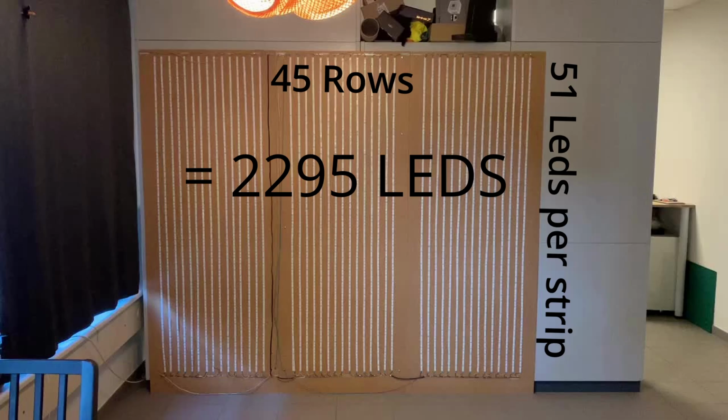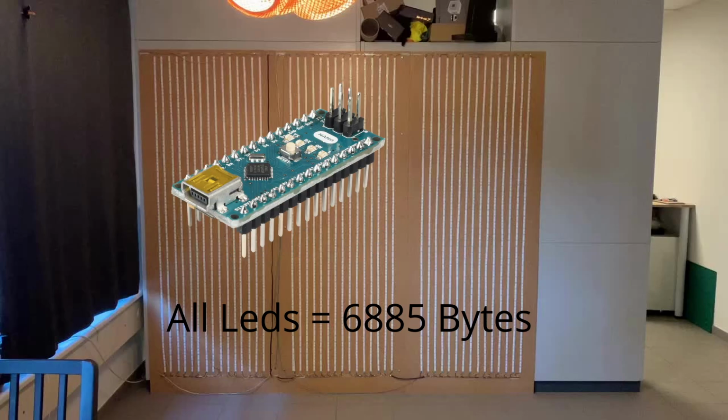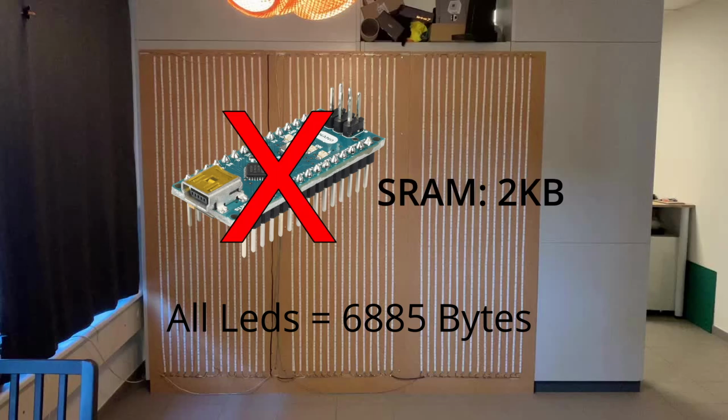Since one LED has 3 colors, red, green and blue, it also has 3 bytes of data. Multiplying this with the total number of LEDs yields that one image is 7,000 bytes big. This concludes that our microcontroller also needs to be able to store these large amounts of data. An Arduino Nano has a SRAM of only 2 kilobytes, so it can't even store a third of one image.